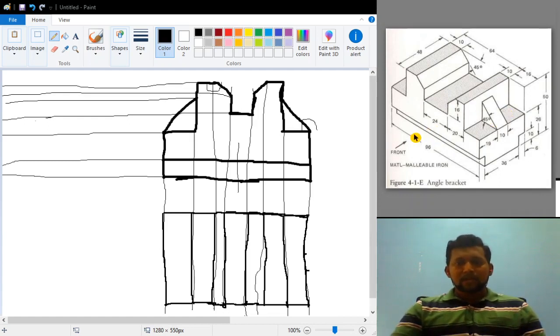Okay, what will happen is, in the top view it may appear like a square. So just join, draw lines like this, which completes the inclined rectangular block on the right side. Similarly on the left hand side also, if you draw something like this, you have completed the lines of the inclined rectangular block, on both the sides.